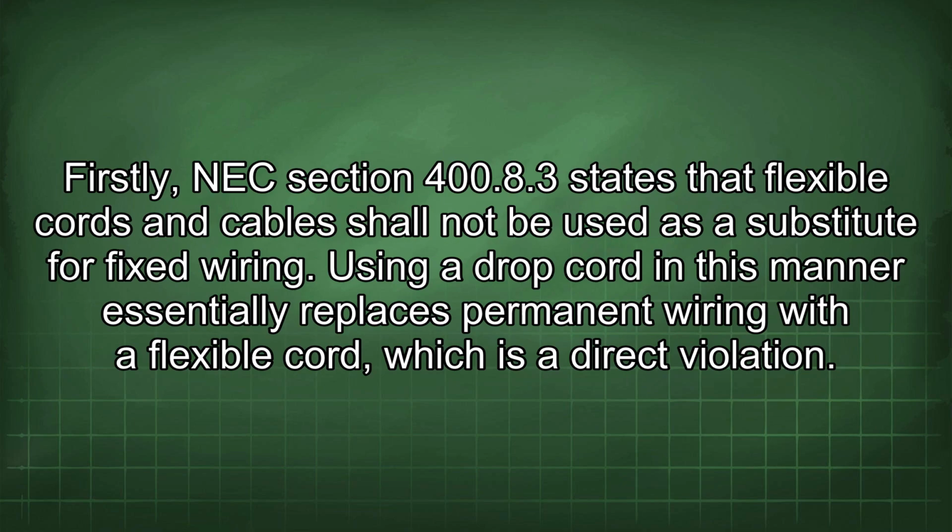Firstly, NEC section 400.83 states that flexible cords and cable shall not be used as a substitute for fixed wiring. Using a drop cord in this manner essentially replaces permanent wiring with a flexible cord, which is a direct violation.